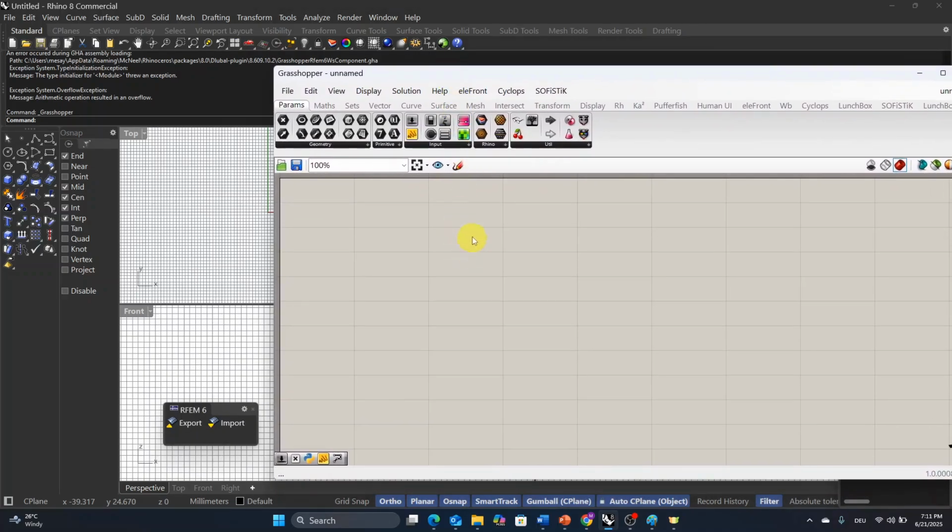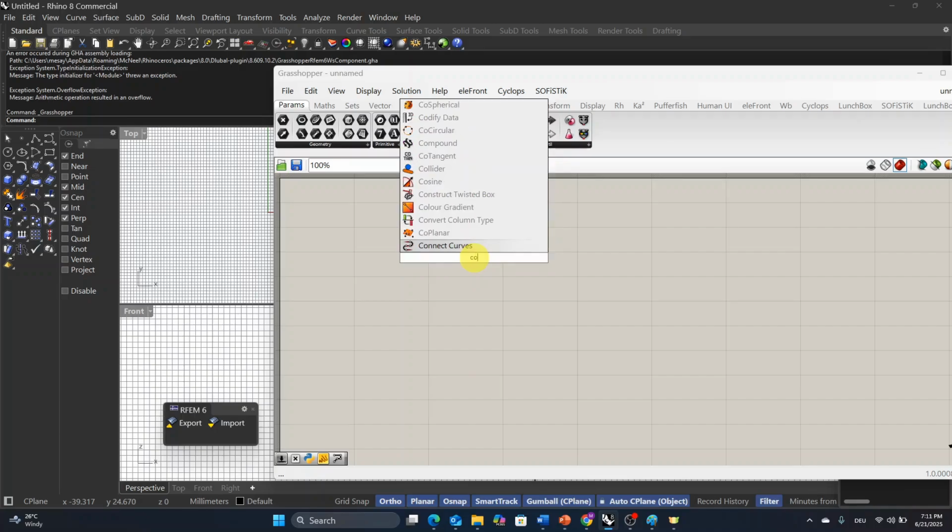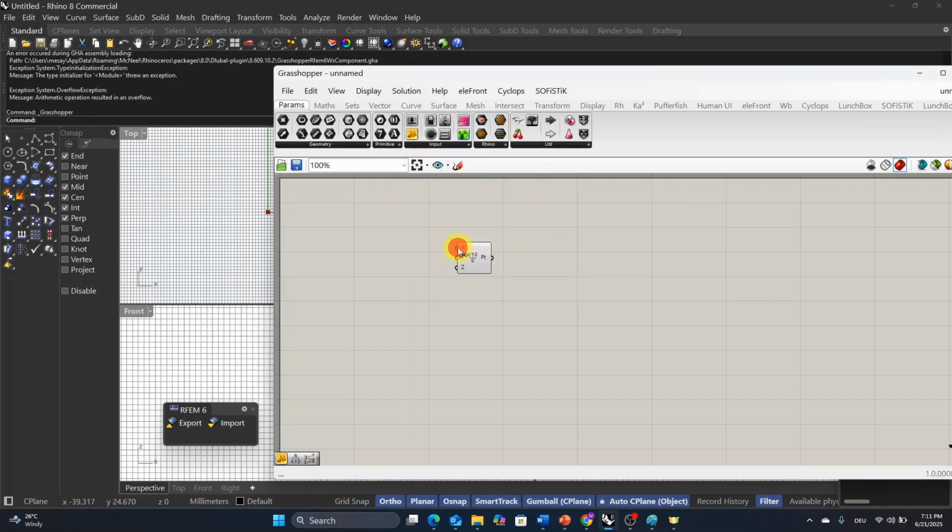At this canvas you can drop different components or commands to perform some actions. Let us use the point component to see the Grasshopper philosophy. When you double-click on the canvas you get a cursor position to write commands. Write construct point on the cursor position and click on the component when it appears. You will see the component appear on the canvas. This component takes three inputs X, Y, and Z and outputs a Rhino 3D point.